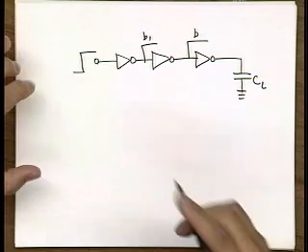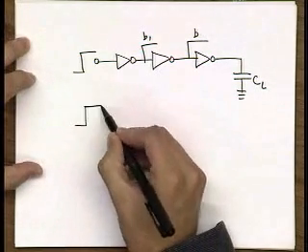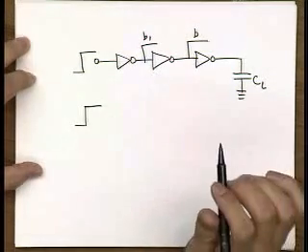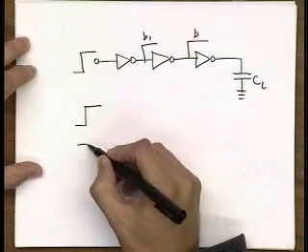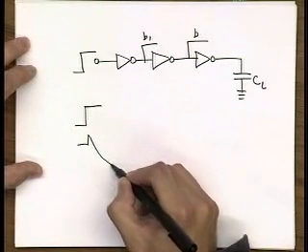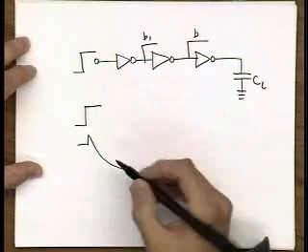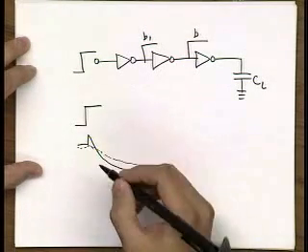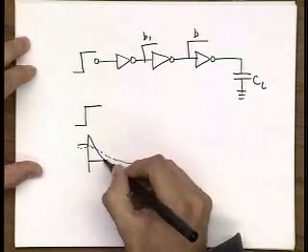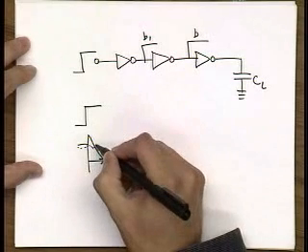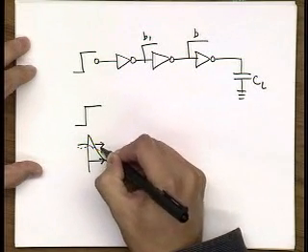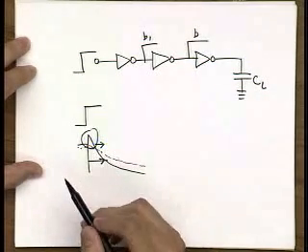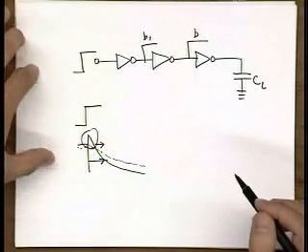But what you actually had, if you apply the step response over here, so you remember from a couple of slides back, due to the capacitive feed-through, you have overshoot in the case of the unloaded gate, and when it's heavily loaded, you have much less of that effect. And when you calculate the delay of the unloaded case, you don't get the delay you would expect, but your delay gets longer because of this overshoot problem. And that exactly comes from this slope problem.